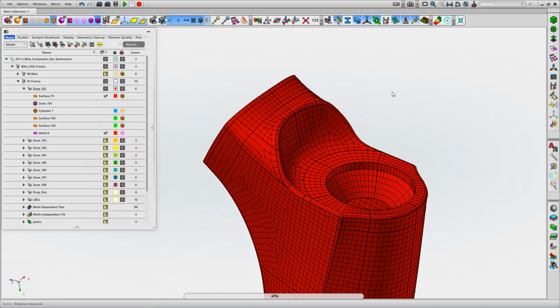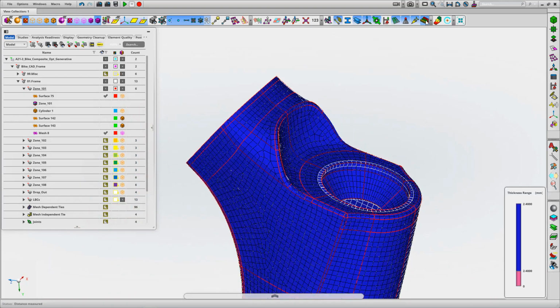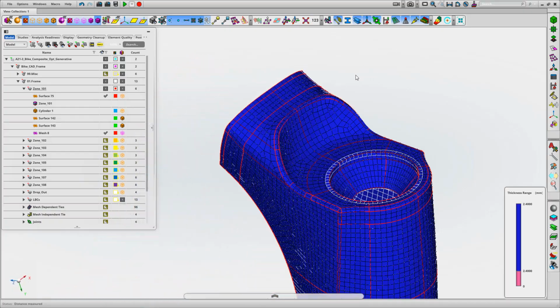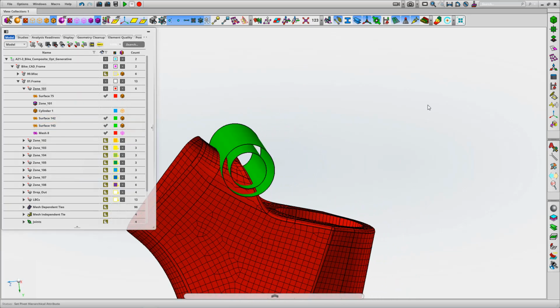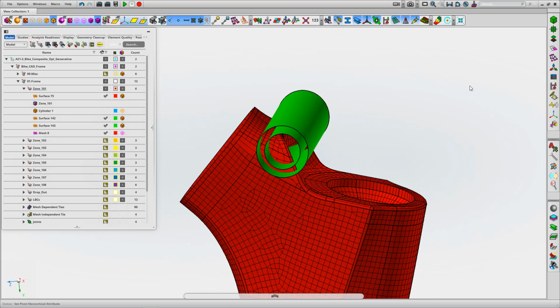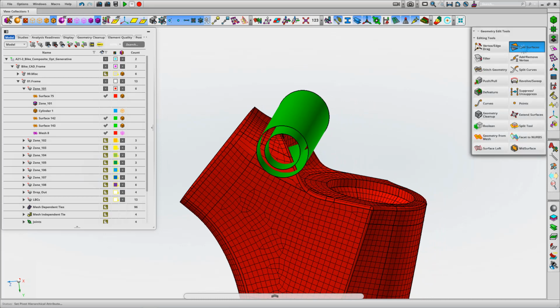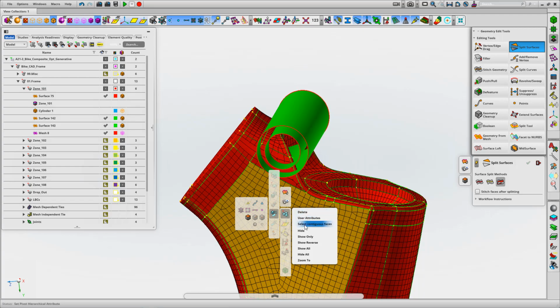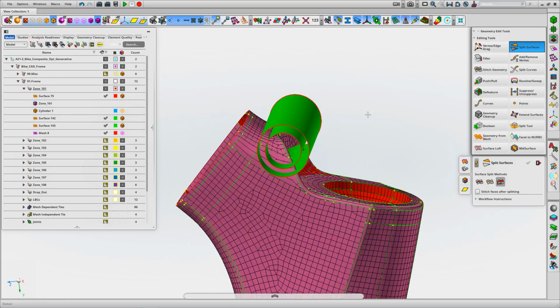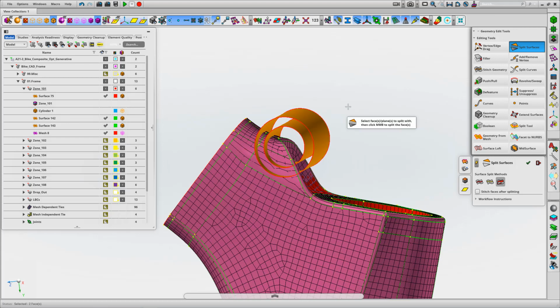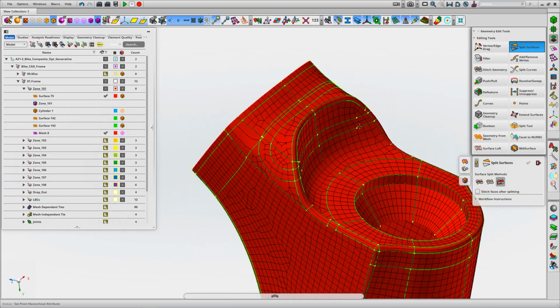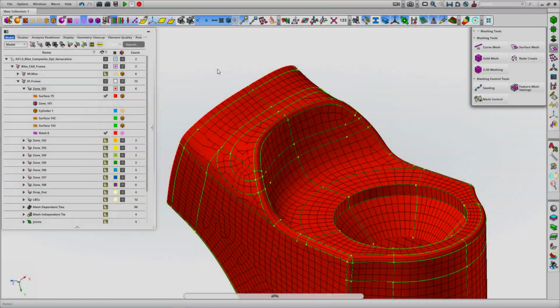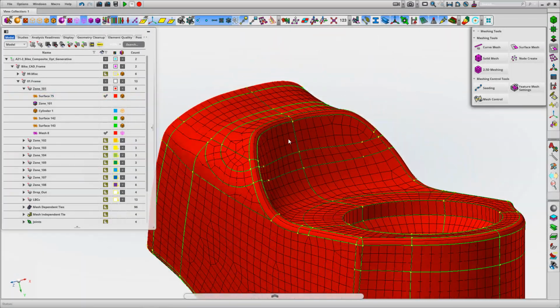Okay. Generative update is something that's pretty important within the Apex environment. So we can look at one particular zone and look at the thickness distribution and definition here. And we're just going to show you how we might want to manipulate the model. So we've just got a couple of dummy surfaces here, and we're going to split the underlying structural mesh or the structural zone definition using these surfaces. And that will give us the new splits in the mesh definition, and then we can look at things like remeshing or changing some of the design features.